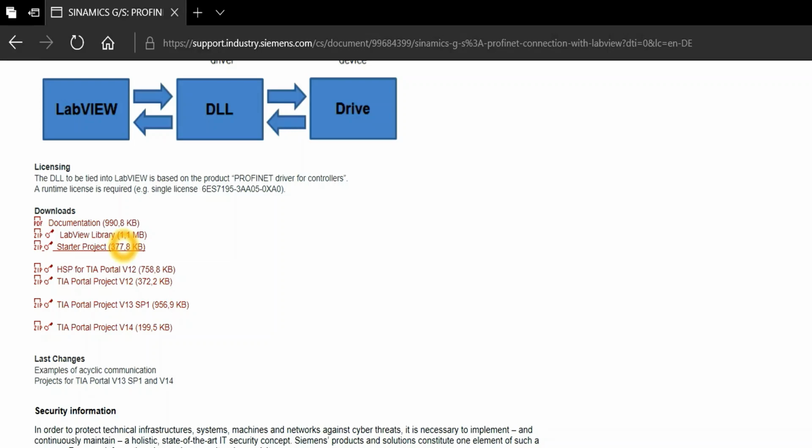Downloading the Starter project, we can start to configure the control unit of the converter: what type of hardware components we used, create topology, select type of communication, and in the end write the project in the internal memory of the control unit. Download the TIA Portal project.